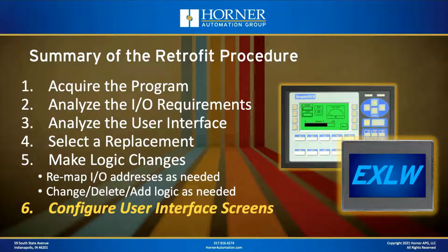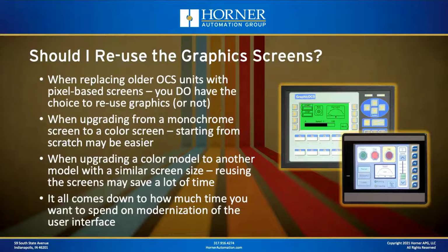Next, let's talk about where most of the changes or the differences lie when it comes to the retrofit procedure, and that, of course, is on the user interface side of things, because the original text-based units had text-based user interface screens that could not be reused, whereas the pixel-based units have graphics which you may choose to reuse. So let's talk about that in some detail. The first thing you really need to ask yourself, though, of course, is, should I even reuse these graphic screens or not from this older project?